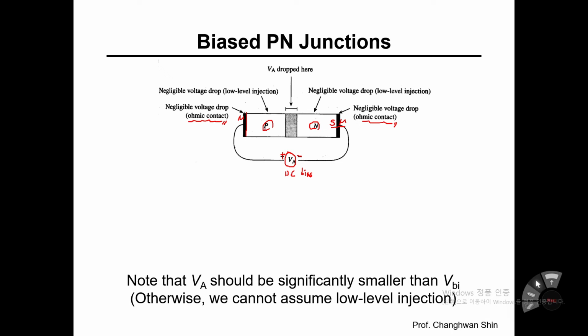Okay, and as we have learned, this p-type silicon and n-type silicon each has its own unique resistivity or conductivity. Just to refresh your memory, the resistivity is defined as 1 over conductivity, denoted as sigma, and this sigma is defined as unit charge q times electron mobility times electron concentration n, plus unit charge q times hole mobility times hole concentration p.